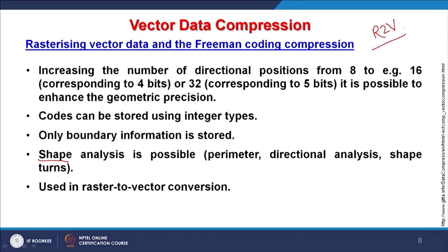So, what we do is we train each and every contour line. We give a start to the software, that this is the start of a contour line having value 100. And then the software itself, by identifying pixels having the same color characteristics, will follow and digitize or vectorize. And wherever there is a confusion, it will stop.